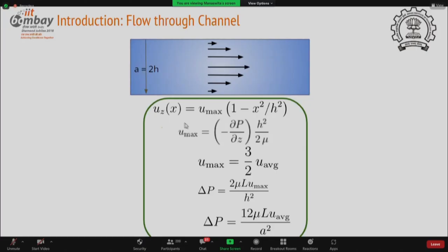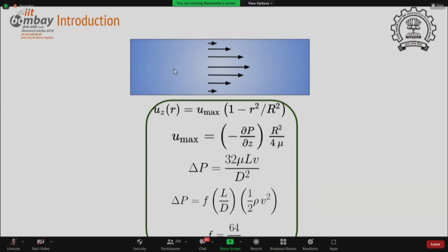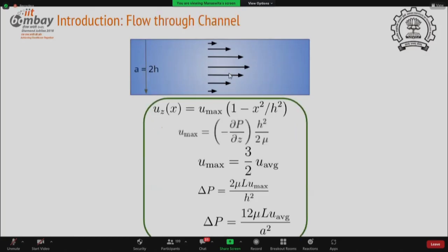And why is this difference? What is this difference due to? The difference is due to the r dr effect. As we move along the radial direction, the area increases in the case of a pipe. Because of this r dr effect, though the schematic representation and planar view are exactly the same, the equations are different. And that we can see from the Cartesian form of the governing equations and the governing equations in polar coordinates, and that's the connect I wanted to make.